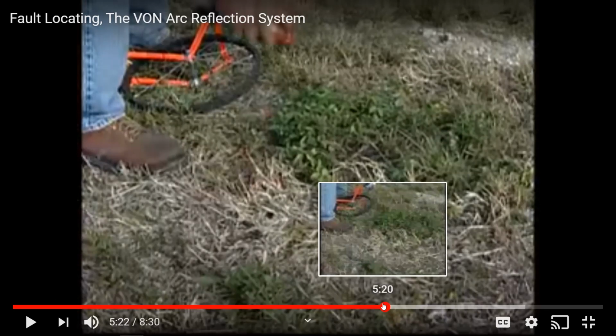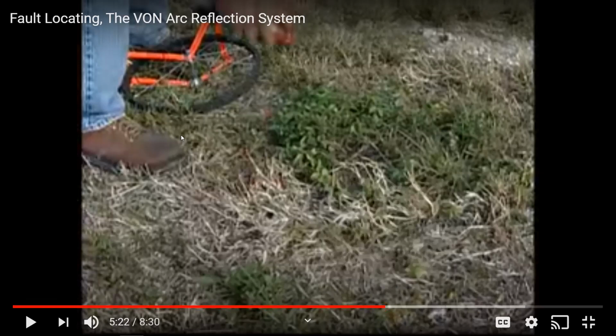You get these and they're really deep. The favorite of linemen to use out there, since the thump is hard to find by sound, is to grab a traffic cone, put it on the ground and put your ear to it, and that'll intensify that thump sound. So he has got a general location by radar with the wheel, and the thump every 11 seconds is going to pinpoint exactly in the dirt where the fault has occurred. All we're doing here is injecting a very high DC voltage, and it's making an explosion in the ground where we have the fault at.